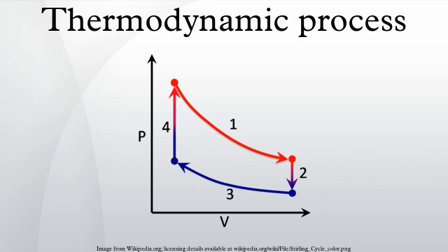An adiabatic process is a process in which there is no energy added or subtracted from the system by heating or cooling. For a reversible process, this is identical to an isentropic process. The system is thermally insulated from its environment and its boundary is a thermal insulator. If a system has an entropy which has not yet reached its maximum equilibrium value, the entropy will increase even though the system is thermally insulated. Under certain conditions 2 states of a system may be considered adiabatically accessible.